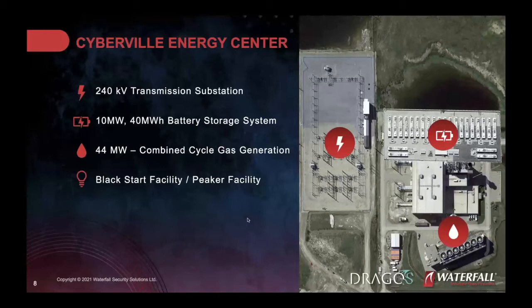Its energy storage systems play several roles within the grid connection, from load following to load smoothing to frequency regulation. And in the event of a serious blackout, the CYBERVILLE Energy Center also plays a startup role. It has large-scale batteries that can be used to fire up a generator to restore grid operations without a power feed from the transmission network or backup source. So this is one of our scenarios here.